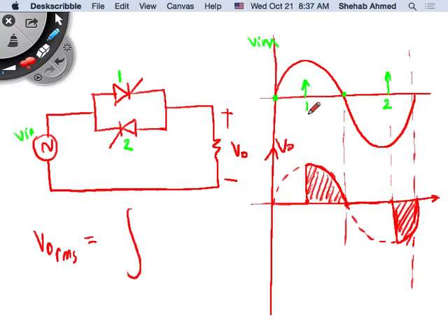If alpha is the same in both cases, so to calculate the RMS value, it's 1 over the period. The period can be only pi, because this is the same value, and I'm squaring the waveform first, so negative or positive doesn't really matter, right?